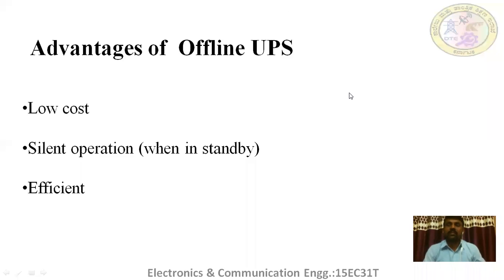Let us see what the advantages are. It is low cost. We know that this UPS is a basic UPS. They don't have protection circuitry, as in the case of online UPS. Also, they will not use any microcontroller circuitry. Therefore, the cost is automatically reduced.